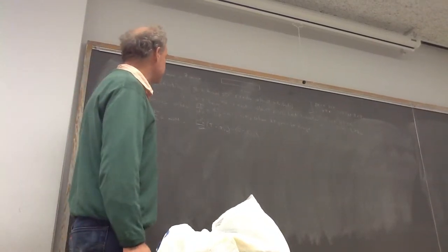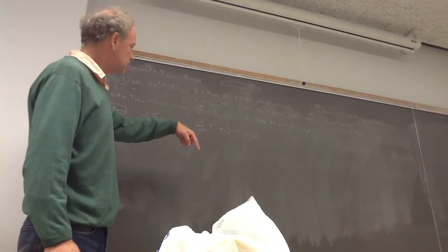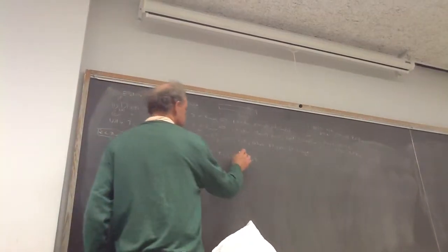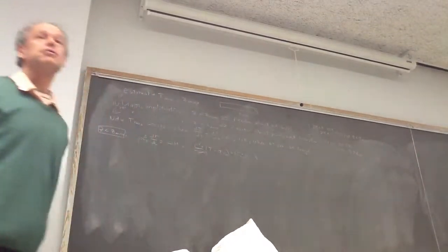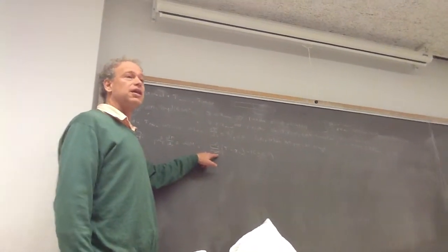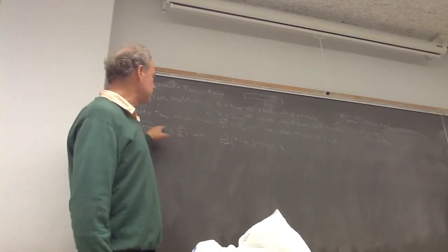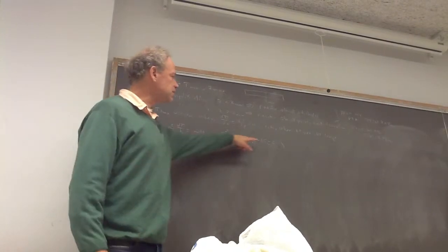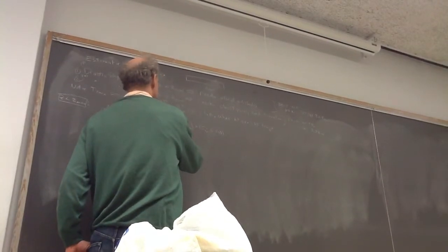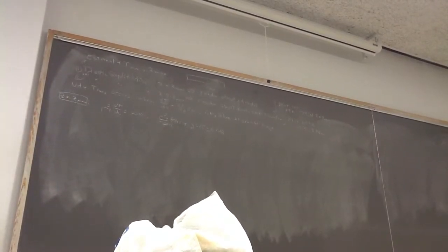And I think I probably screwed something up because there's probably a negative sign somewhere. The concentration's going down and the temperature is going up. So I probably want a minus here and then put the minus here: C inlet minus C. Because this is an exothermic reaction, delta H is negative, so minus delta H. So I just multiplied by minus 1 squared. I put this minus 1 here and minus 1 here. Okay, now this is positive, and in particular this is C of Z. So I see that T and C are linear in each other.